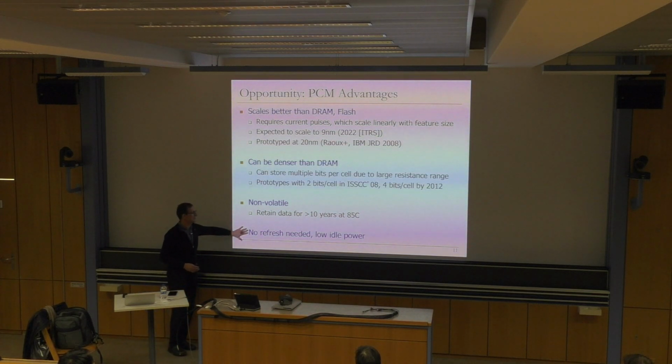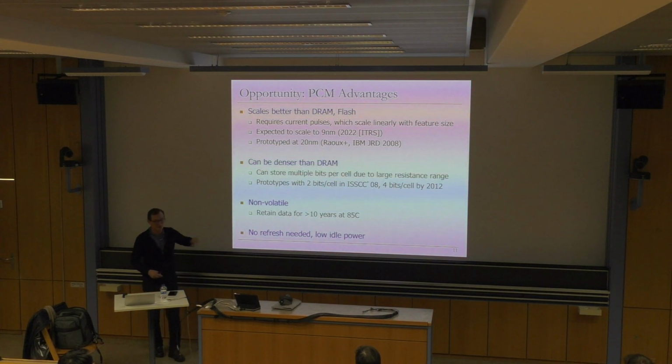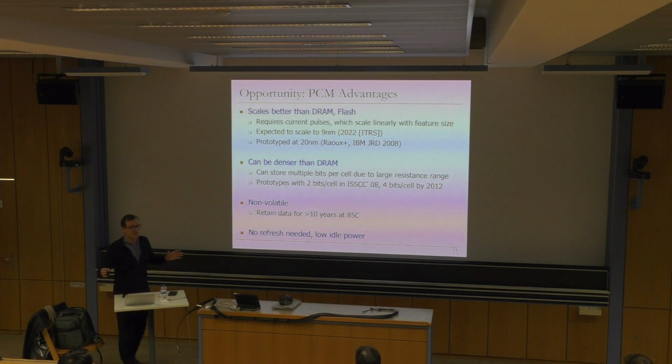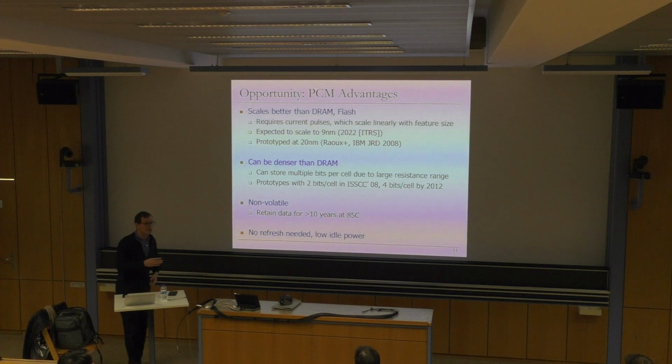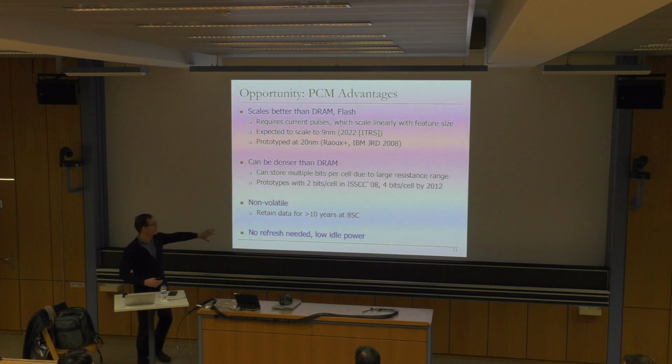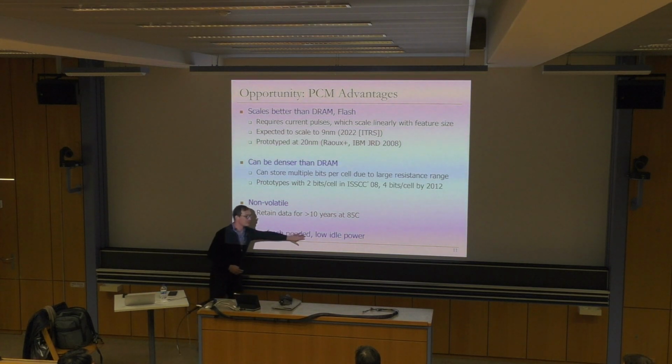And in this case, it's actually not clear what the scale is exactly, because there's not good enough data in the field related to this. But it's similar to flash as opposed to DRAM. Low idle power is important because charge leakage is much faster in charge-based memory. Here we're based on resistance. So the static power is very, very low in these sorts of memories.